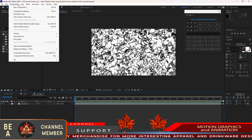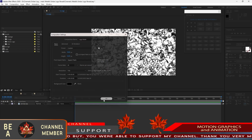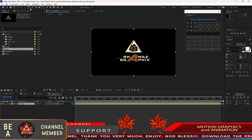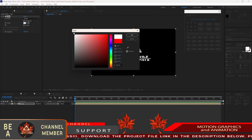Go to composition, create a new composition. I will name it logo matte. 3840 by 2160, 30 frames per second and 20 seconds duration, click OK. Then highlight this logo, drop it down into the timeline. Go to effects and preset, go to generate, go to fill. Change the color here to white, click OK.